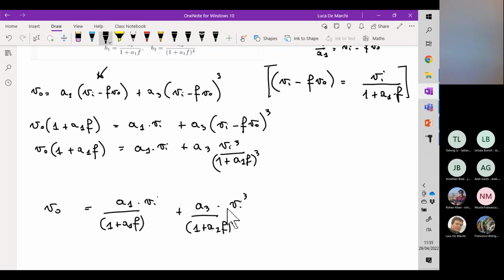Relative frequency here means omega over omega null, essentially. At 45 degrees, you see there is this quite pronounced overshoot. With a smaller phase margin, you have an even larger overshoot in the global frequency response. And as you may imagine, when the phase margin is even smaller than that, you will have a very large overshoot. At the end of the day, if the phase margin is null or negative, then you will have such a large overshoot that you will get instability.